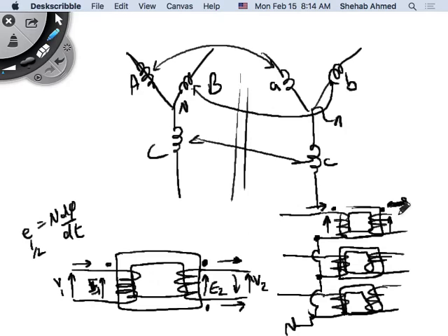Okay. Same thing with the delta, right? Exact same thing with the delta. If I would connect it instead of this way, I would remove this connection to the neutral and connect the 3 windings in series and create a delta. And I have a picture of that in the slides. And windings on the primary and the secondary that are on the same core are in phase, so we will see that everything on the primary side and everything on the secondary side will be in phase.